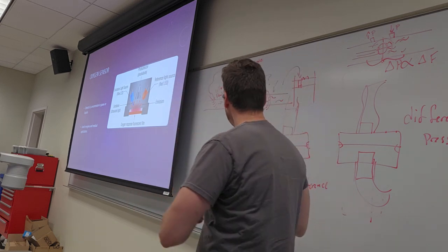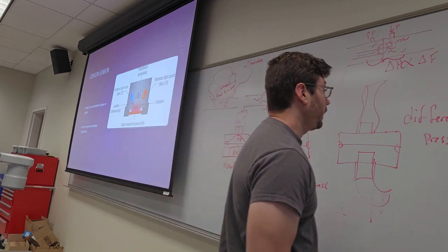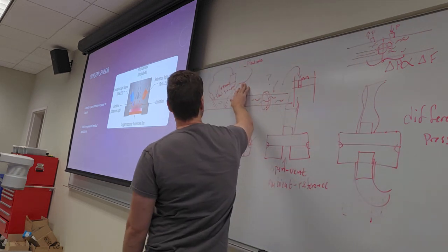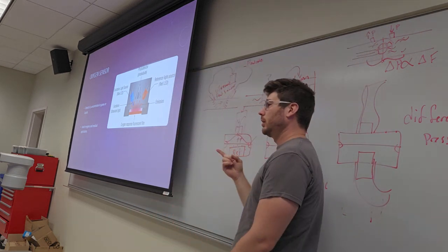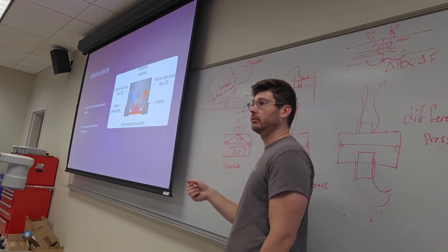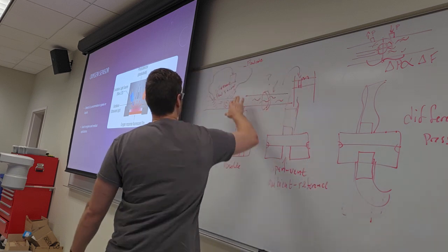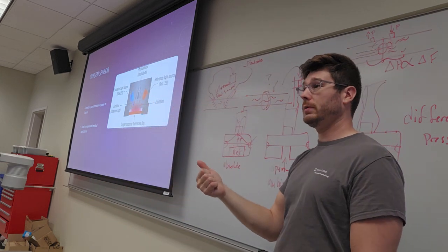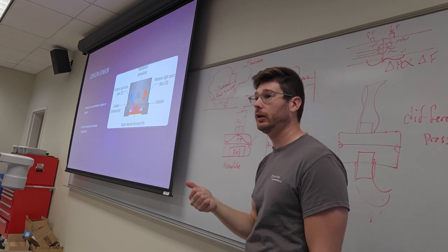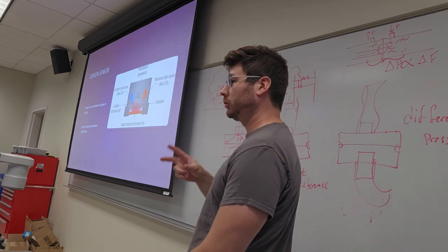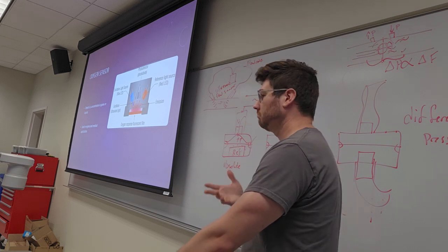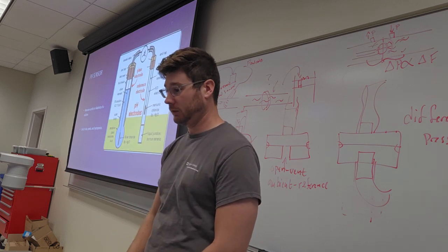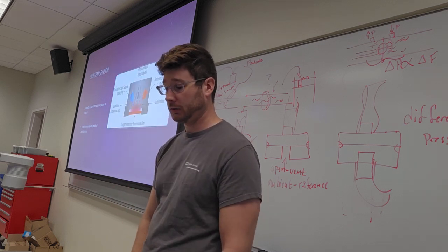Okay. So that's a good point to whip back, is that all of these sensors, flow sensor, pressure sensor, ultrasonic sensor, right, they might give us the exact same parameter. It's just a number, flow rate or pressure or whatever, right? And then it's up to the individual sensor and its interface on how to connect to the PLC, right? Is it a simple analog reference, which might be just a single wire with an analog voltage on it? Is it talking UART, you know, actual human readable data that it just spits out every second? And that happens pretty often too. Okay, it's up to you guys to take that data out of that device and get it into the program.